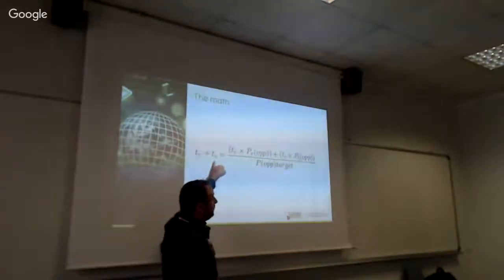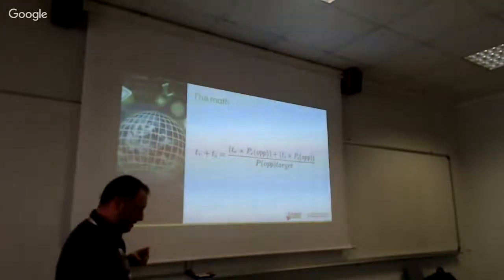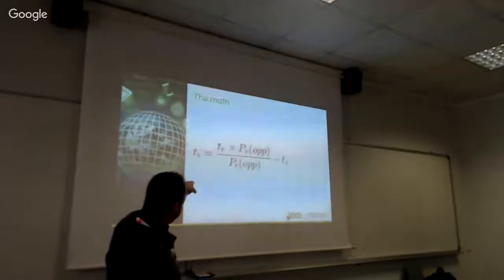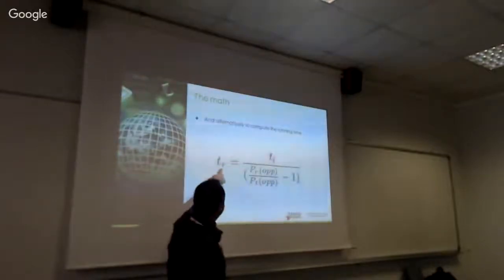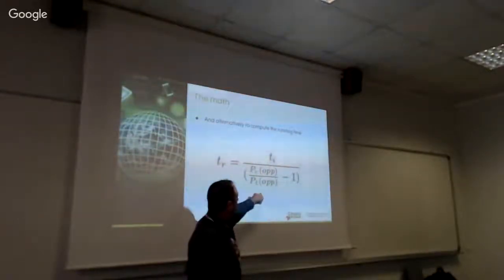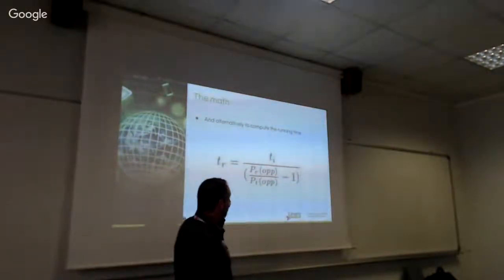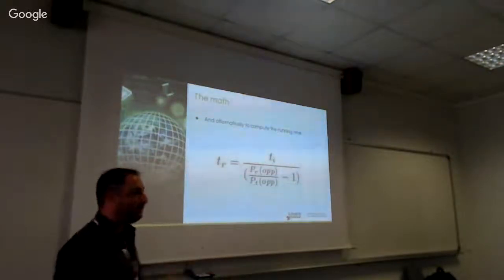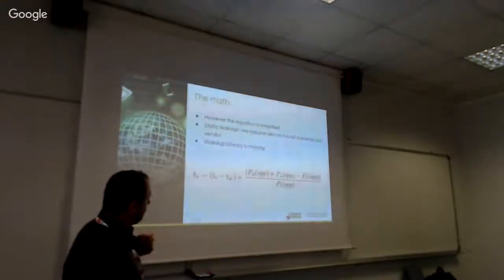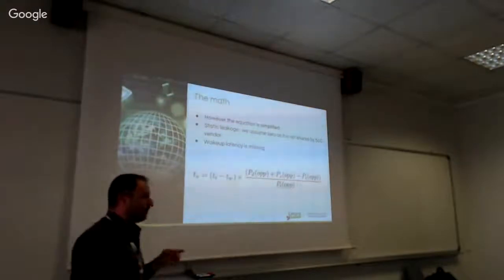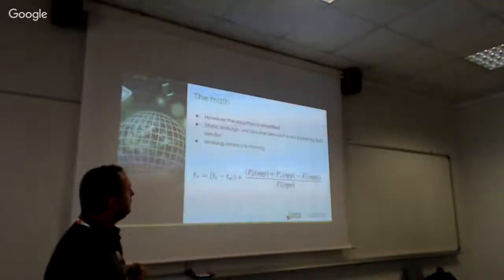So we know the time we will be idle. For example, we say it's 10 milliseconds. And from there, we can rearrange the equation to get the time idle or the time running, with all the information in there. So the power of the different OPPs, we can compute directly from the DT because we have all the information. The idle duration, we know this information because we decide how long we will be idle.